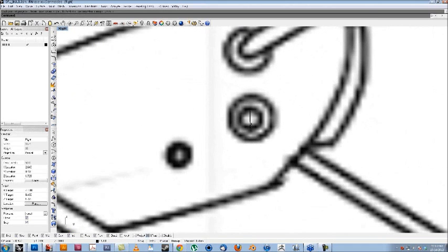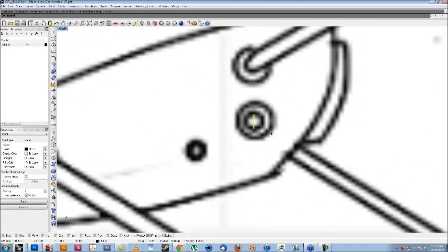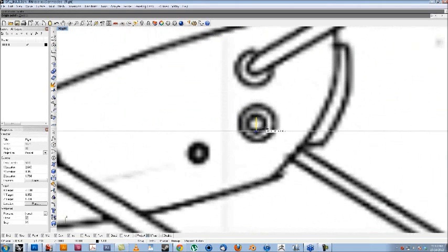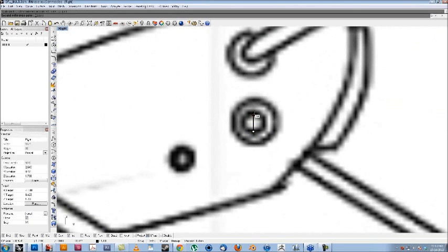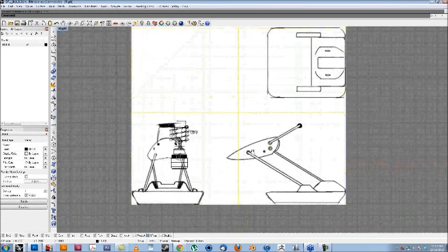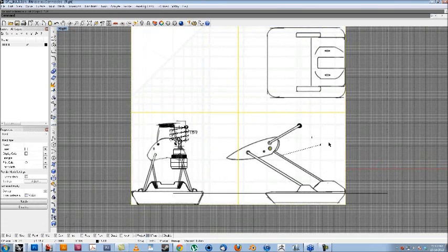So if I just draw out a line that represents the diameter of that and select my surface, I can then type scale and say 0.125, and that'll get everything perfectly to scale of how I need it to be, and then you can trim it all back.